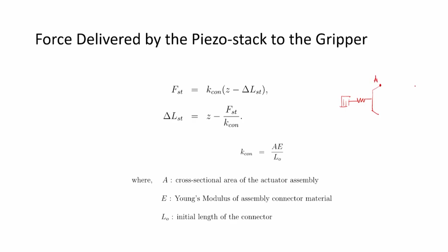the grasping system. So, the force that is going to come up is K times the stiffness of the spring K, and then the difference between this movement here and the movement at this point, that means the relative displacement between the two, is what is going to give us the force that this is going to apply into the grasper.